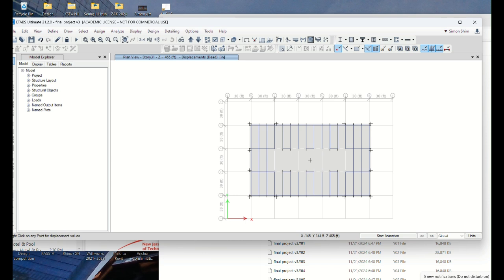But typically we don't introduce an intermediate node between the floors, so usually it's okay. But if you happen to have a node, if not using this brace frame, sometimes we have a different configuration and end up with point nodes between the floors, you need to double check whether that intermediate node is included in your diaphragm or not.